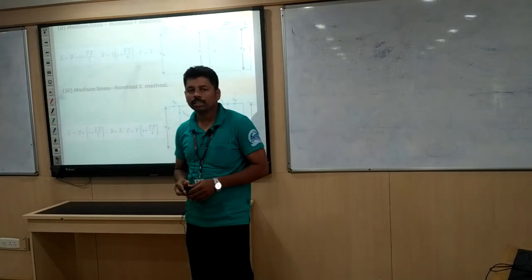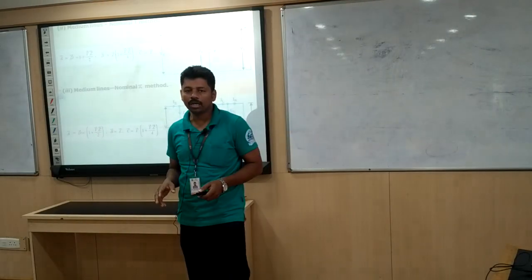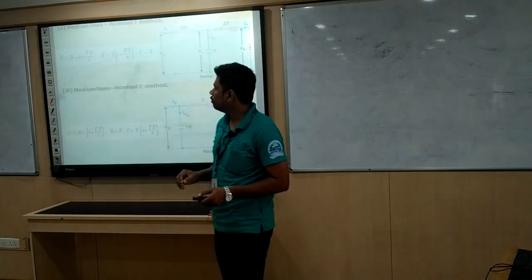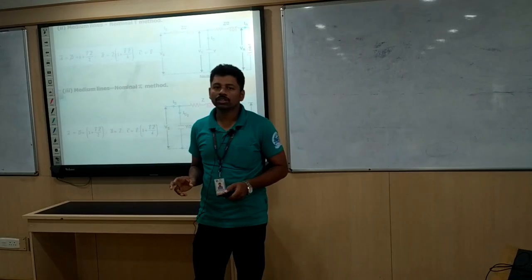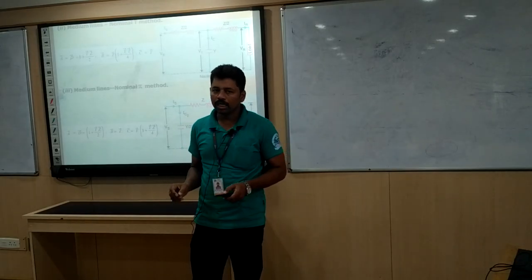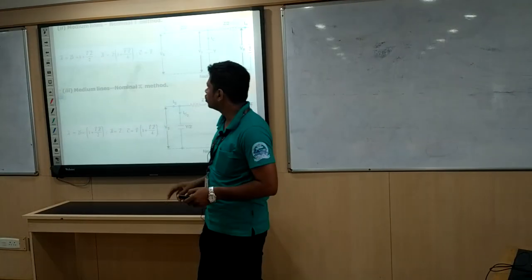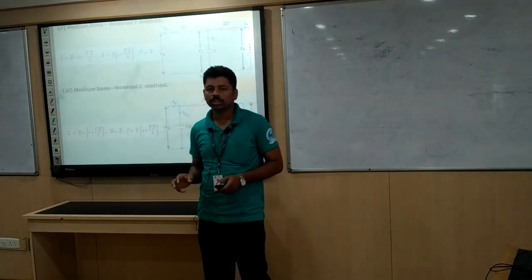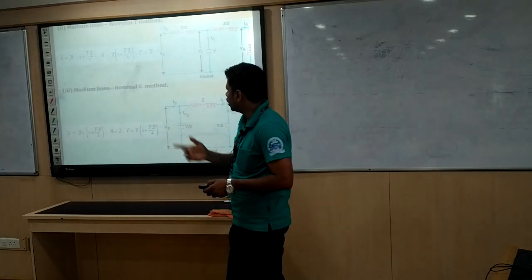Then coming to the medium transmission line, directly we are starting with the nominal T method. The reason is, in the end condenser method, both the conditions are not satisfied. Even though A is equal to D there, the AD minus BC condition is not getting satisfied. So that is the reason we can't frame the ABCD constants for the end condenser method in the medium transmission line.